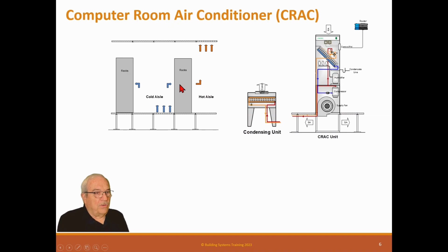Now the trend has always been that the computers get smaller and smaller, more and more dense. So we get a lot of servers, but unfortunately the heat inside the server rises. What's happened over the last 3 or 4 years, which has been good: we used to say that the computer people wanted 72 degree air minimum into this unit. Colder is better, but not hotter. Well, nowadays they've realized that they can live with up to 90 or 95 degrees at the server itself. So they've allowed us to raise these temperatures, thus saving energy.